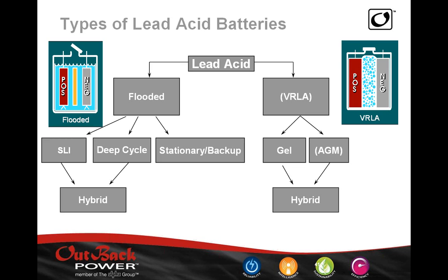But with today's designs, AGM batteries are now getting to the point where they can compete on cycle life, and they actually outperform flooded batteries on float. They are maintenance-free. The VRLA batteries, both gel and AGM, do not require maintenance, and by maintenance, I mean the addition of water, whereas flooded batteries do require the addition of water.